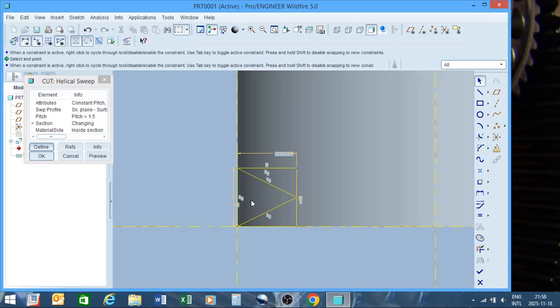If there's any loose ended lines, it will show you, and it will show you if it's open. So I'll show you now. If I click here and I push delete, see it shows me there that that line does not have a connection. So once I click delete on that one, you'll see the block will actually highlight. There we go. So that is how we know that our block is complete.